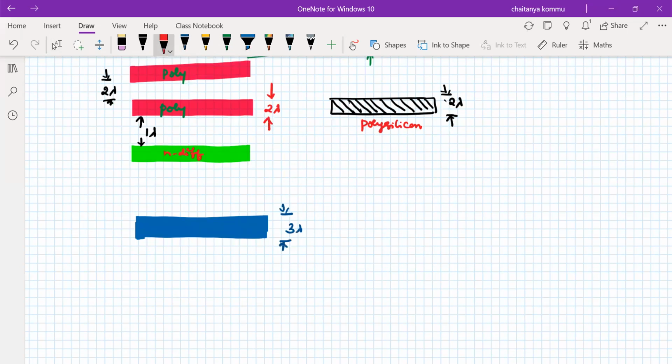It is metal 1. Metal 1 is in the first level, like polysilicon and diffusion. Metal 2 is also there, which is above metal 1. Normally we consider metal 1 only. So for metal 1, the minimum width must be 3 lambda.